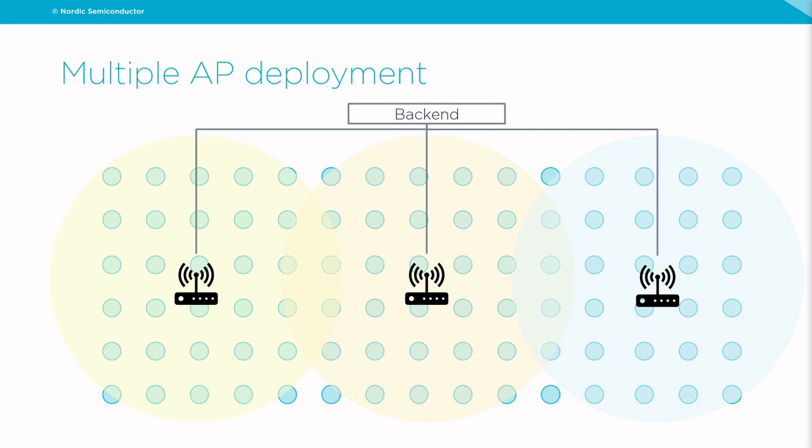If you can tolerate higher latency, for example, if you can tolerate that you can ping and change images of all tags within 10 seconds, then you can have more devices for each access point, and you can have more tags per each group, more than the number of response slots. You can have naturally more devices as long as they are within the radial range of the access point. All of these are indeed design choices that you will need to make when you deploy a system.